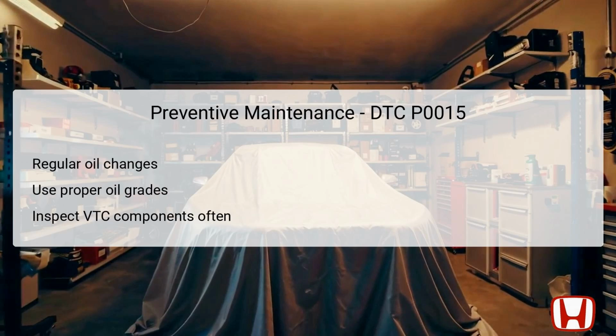To prevent DTC P0015 from occurring in the future, implementing a routine preventive maintenance schedule is imperative. Regular oil changes using the manufacturer-recommended oil type and grade can significantly minimize the buildup of sludge and debris within the engine, helping the VTC components function smoothly.